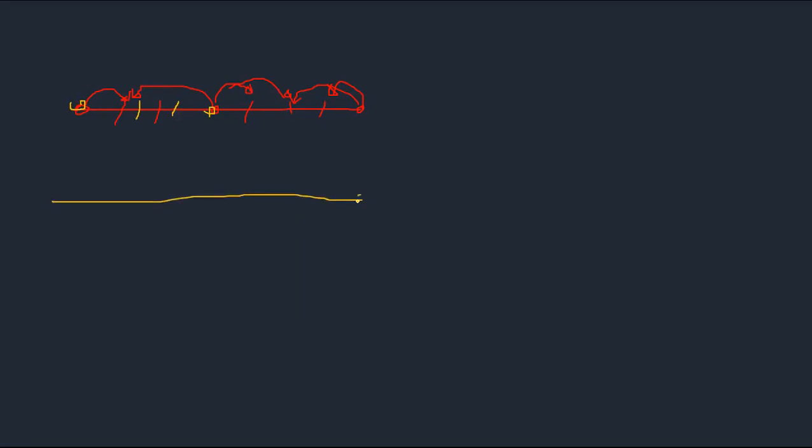So when you increase the number of nodes, any of these locations will be given as a function of this displacement and a function of this displacement. So this is interpolating between a larger segment, but this is interpolating between a smaller segment. So this is more accurate, right? This is being more accurate.